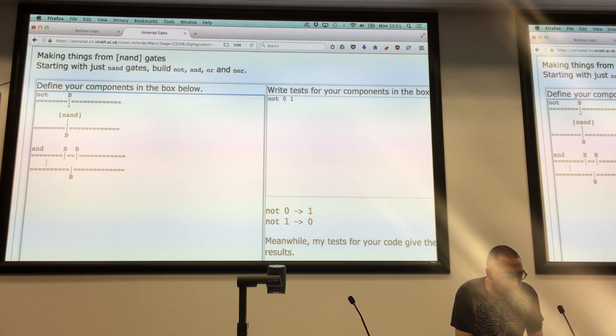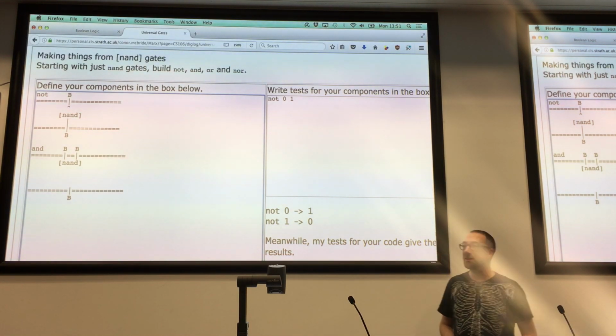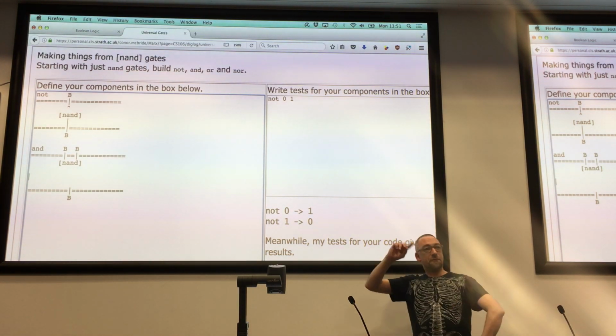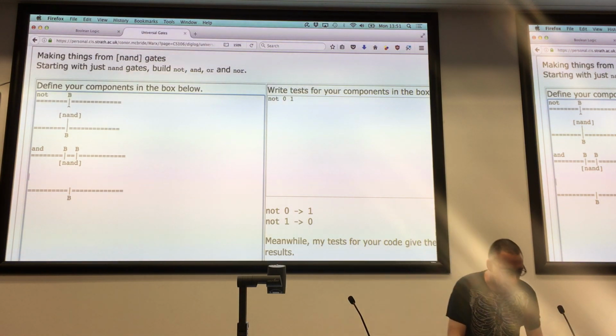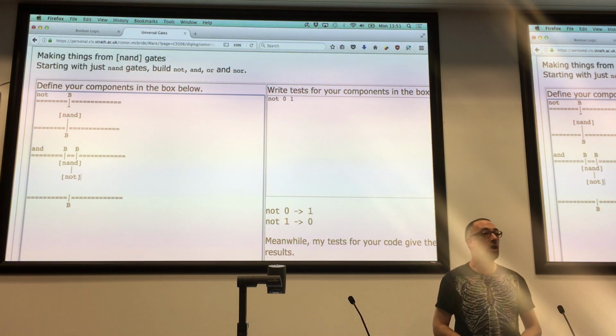We know how to make a negated AND, so how would we make AND? Negate the NAND. Yeah, negate the output, sort of flip it back over. That should give us back an AND. So we can wire the output of NAND into, and here's the good news, you could wire it into NOT, because we've already explained how to make NOT.